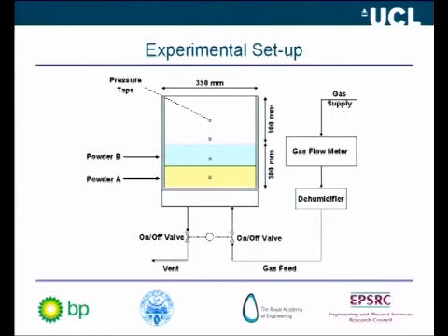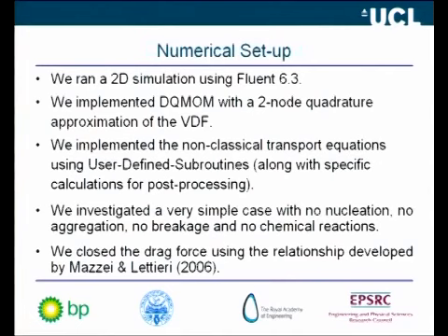We took the powder from each horizontal layer, and we sieved the powder. Then we compared the particle size distribution of each layer, and we checked that for each layer we obtained the same particle size distribution, which means that the bed was very well mixed. Our aim was to predict this evolution of the particle size distribution using the model that I presented before.